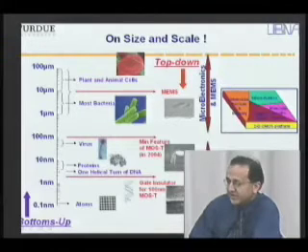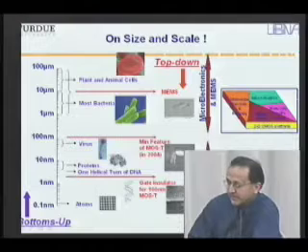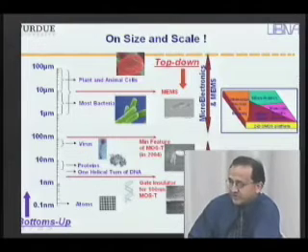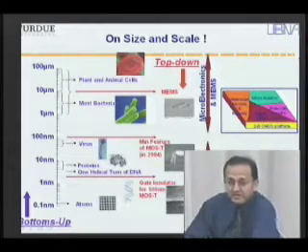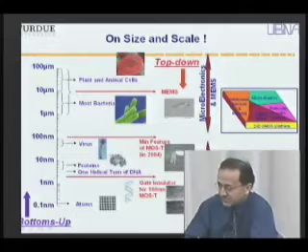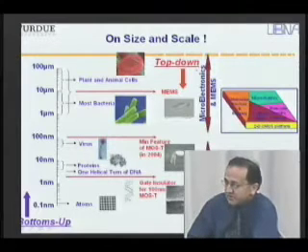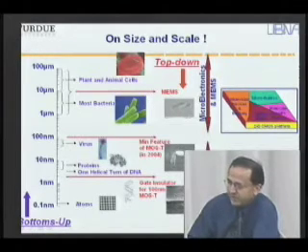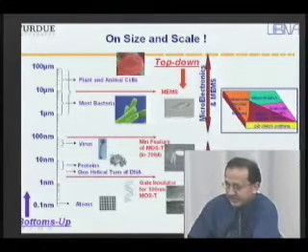Things on the right here in the middle really are these top-down structures. These are structures that have been fabricated using top-down techniques, which means that we have fabricated them from a larger structure and made them smaller and smaller. So most microelectronic and MEMS structures might be in the range of 1 to 100 microns. The minimum feature of a MOS transistor in the year 2000 is actually a little bit below 100 nanometers. This is in commercial production.